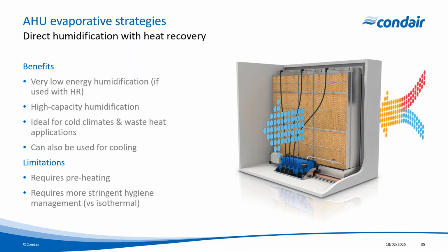So just to give you an idea, 200 pounds of humidification done through a traditional electric or isothermal steam system is going to require about 75 kilowatts of electricity. Our evaporative system, on the other hand, if you can evaporate the amount of water, can actually output about 2,200 pounds of humidification, which in the end would consume less than 0.3 kilowatts, because the only energy that we're putting into the system is the energy to run the pumps to pump water to the top of the media.